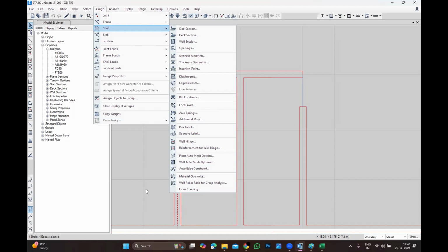There are non-load bearing walls and there are load bearing walls. The hollow core slab will never rest on a non-load bearing wall. It will rest only on a load bearing wall. And you will have a cushion from the load bearing wall to the hollow core slab, like 30 millimeters, 40 millimeters, 25 millimeters, with sealant, in order not to transfer the load to the non-load bearing wall. That is the reason we keep this cushion. It will never touch the non-load bearing wall directly. If it touches, then you're changing the behavior, and a portion of the load goes to the non-load bearing wall as well.